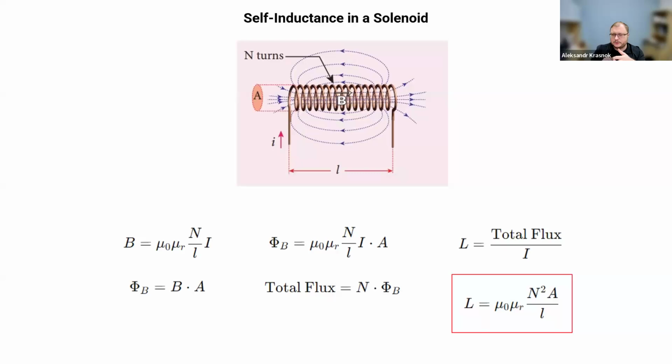In many applications, you need to reduce inductance. For example, in CMOS electronics and processors, people avoid any turns. The less deformation of wire, the better, because any deformation, any loop, any bend will unavoidably create stronger inductance.